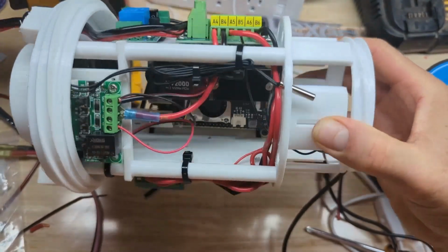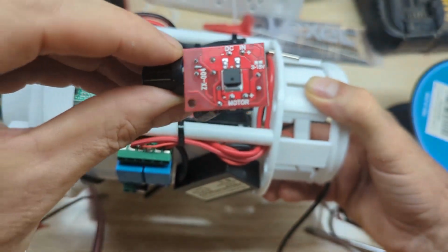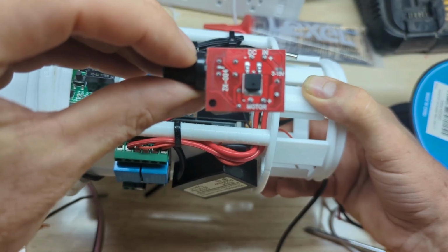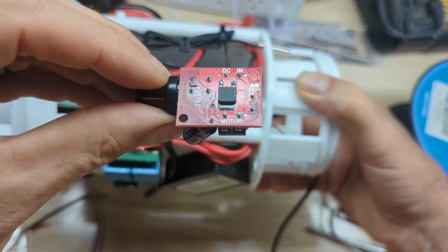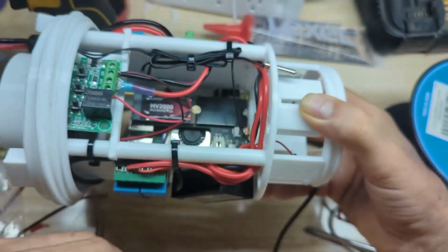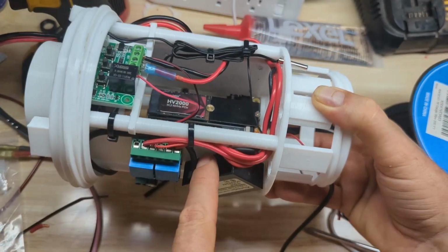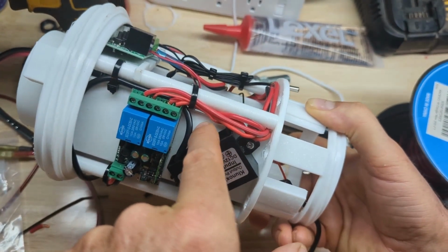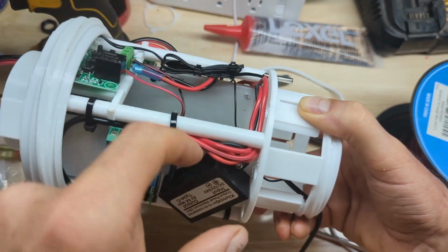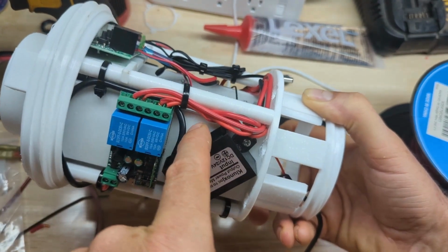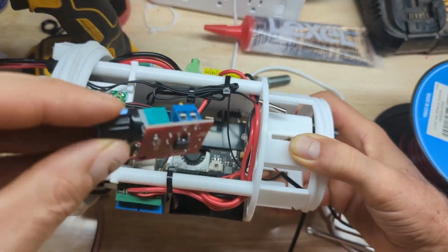And I'm thinking probably we've got this little gap right here. If you'll recall, this PWM controller only has a single hole right here by my thumb where it mounts to something. We're going to use a double-sided tape pad for this, plus that screw to keep it secured to the wall. But I'm thinking probably right here, mount it right there, because there's a little void right here beside the Raspberry Pi power supply. We can screw through on this side and make sure it doesn't hit anything on this side. So I think that's where we're going to go with that, and I'll get it all wired up and we'll anchor it in.